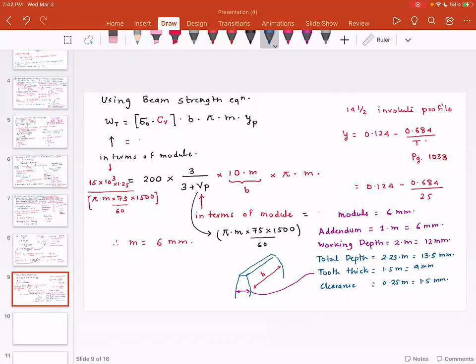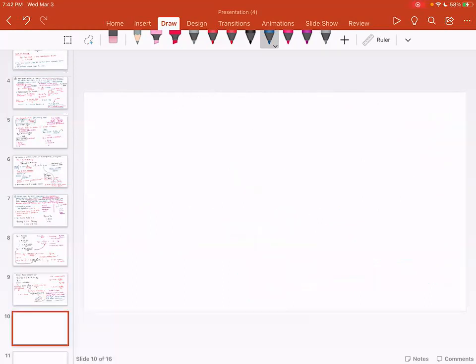Now, with this, you have the gear or the pinion designed. With this information, you should be able to sketch the pinion. You should be able to use SolidWorks and create a model of the pinion. The next important part is shaft design. So let me consider this shaft design. And as discussed earlier, the configuration of the shaft is not known. So we do not know whether the gear that we have is cantilevered or simply supported.